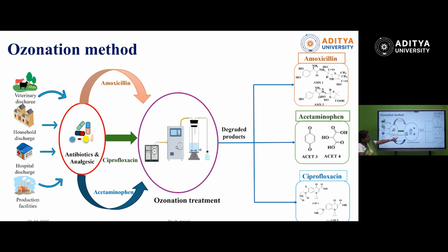So O2 is supplied, O2 is converted into O3, and the O3 goes to the reactor. The sample you can see here is the three pollutants mixed in the reactor. Then the liquid ozone is added to remove them. Another thing is there, to check the excess ozone, how much excess ozone is being released. Generally a KI solution is used to detect that.